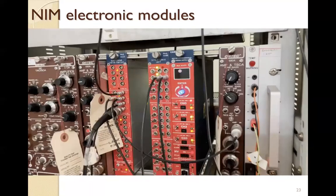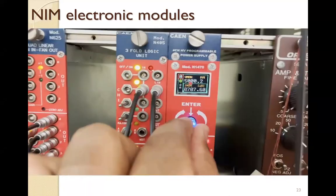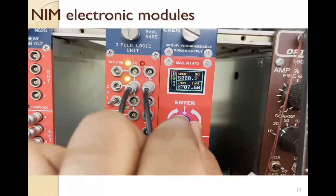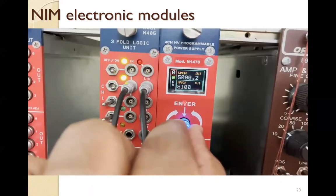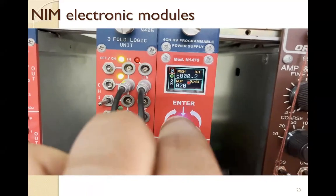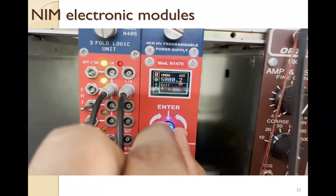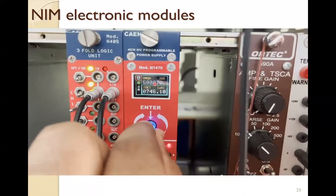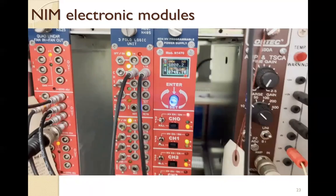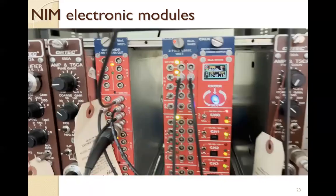So you can see some electronic modules are there. This is the high voltage module. You can see there is a model number. We use model N1470, where using these knobs, I can do many things. I can apply voltage. You can see Vmon, this means the voltage which is monitored, which is 500 volts. Some currents are there, and there are some other modules.